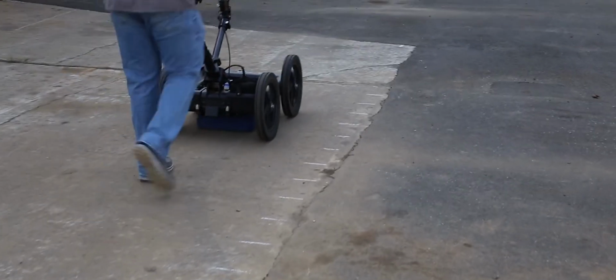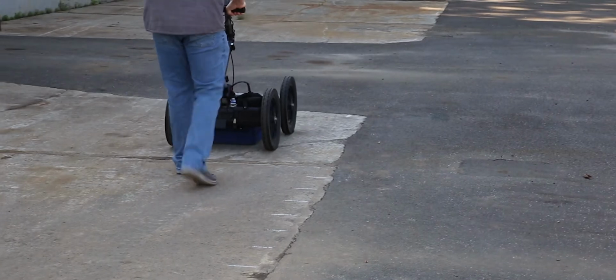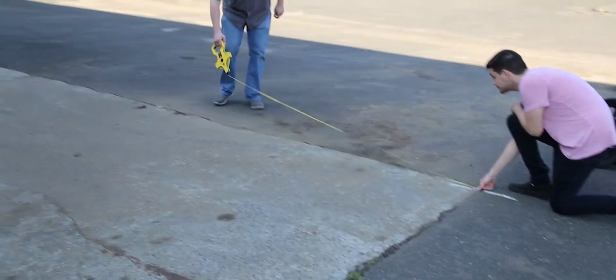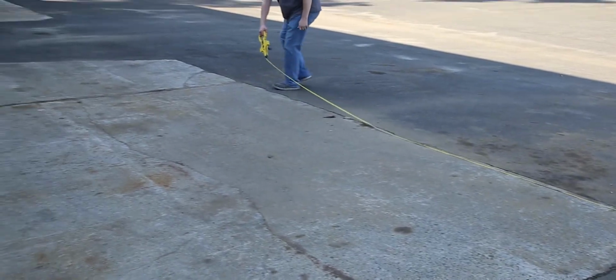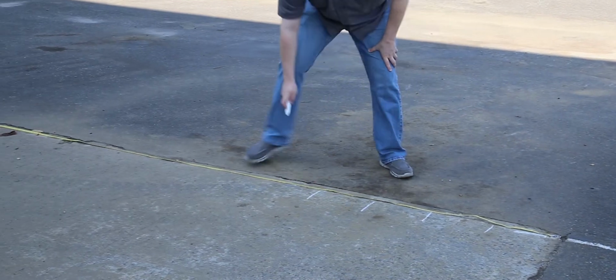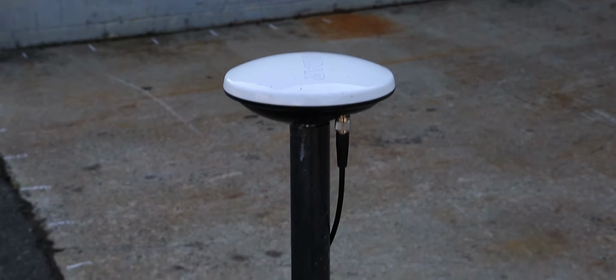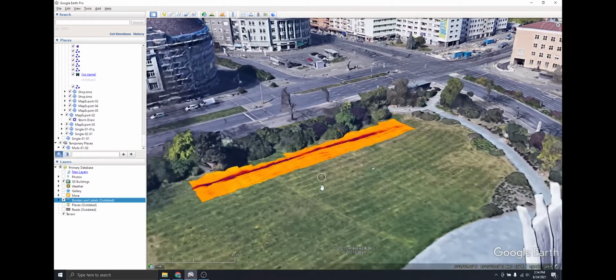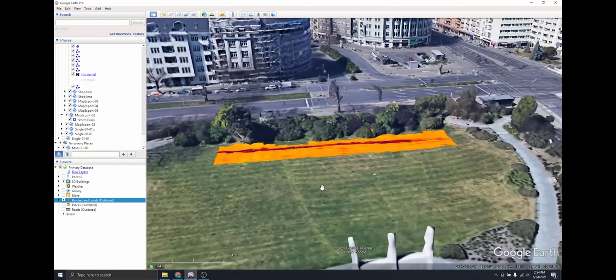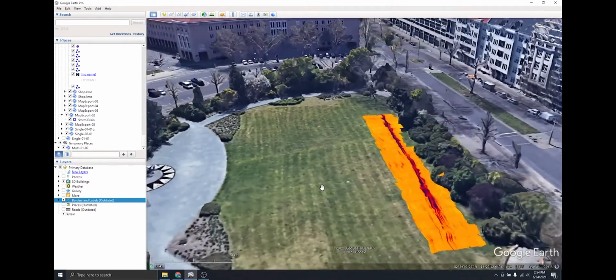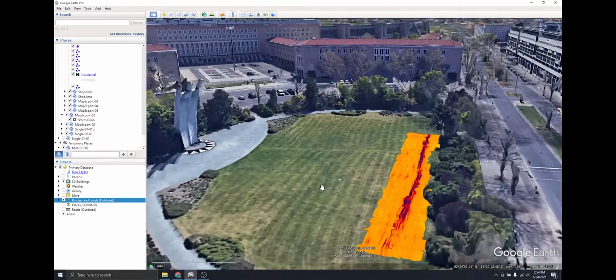If you are planning on completing a 3D survey, you must prepare accordingly. You will not get usable results by guesstimating your grid pattern. You must measure and make physical marks. While it is not necessary to use a GPS receiver when carrying out a 3D survey, it does enable a completed peak map or slice to be exported to third-party software, such as Google Maps.